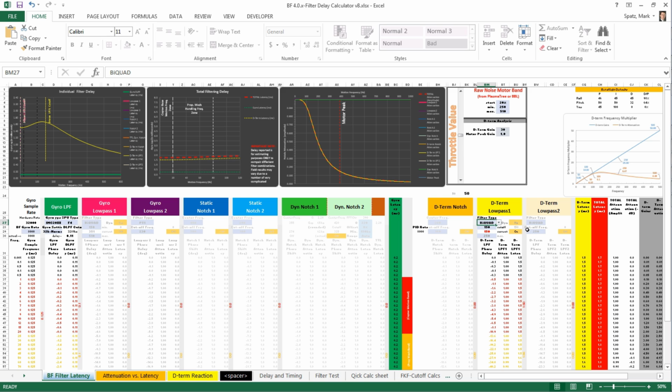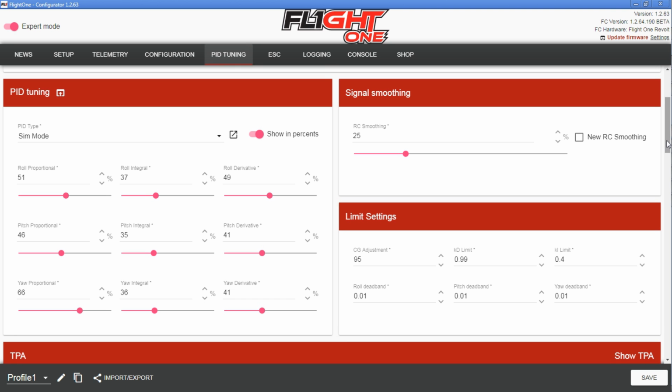To me, it's usually half and half. Usually about whatever your gyro latency is, usually about 2 milliseconds here, or 1.5 milliseconds here, and then 1.5 or 2 milliseconds on the D term total latency. Okay, now back to the firmware. So the higher your D gains or P gains, the more filtering you will need. So everything's a trade-off. I wish it was simpler, but it's just not.